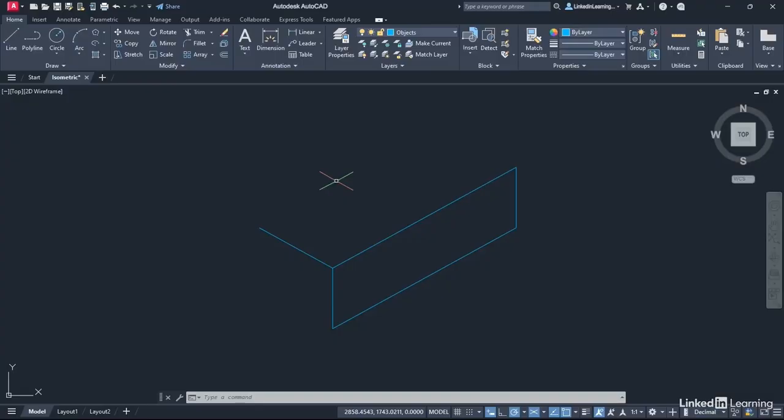Now you'll notice the crosshair looks a bit different. That's because we're using the isometric drafting in AutoCAD. Now in the previous video we did the ellipses using that 60 degrees isometric rotation tool in the ellipse command. That's what we're kind of working towards in this drawing, but we're actually drafting in isometric, which is normally at angles of 30 and 60 degrees.